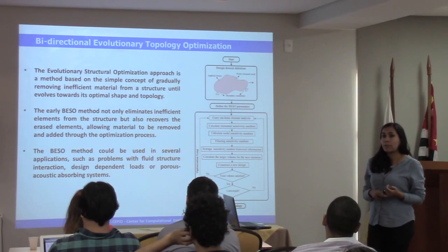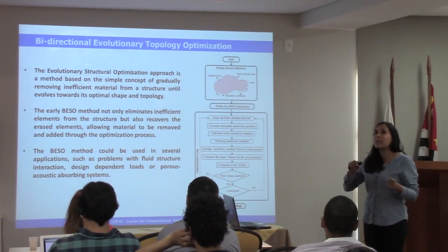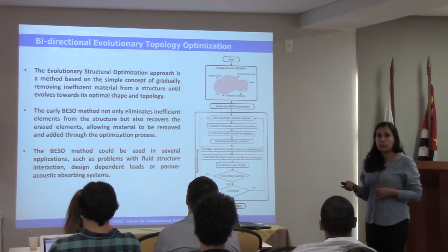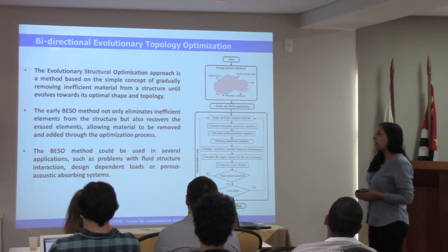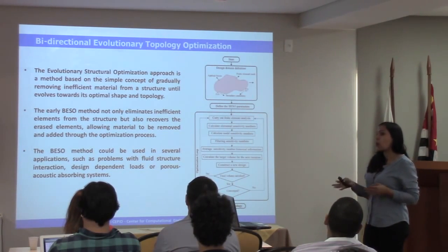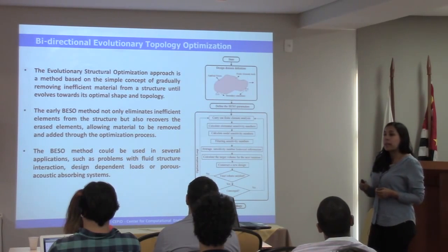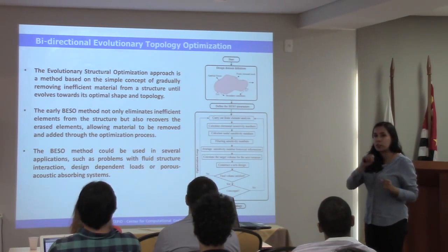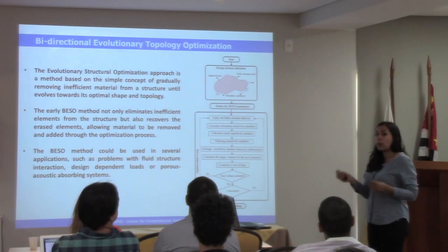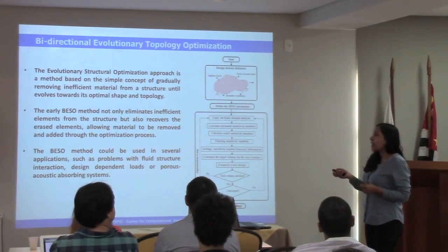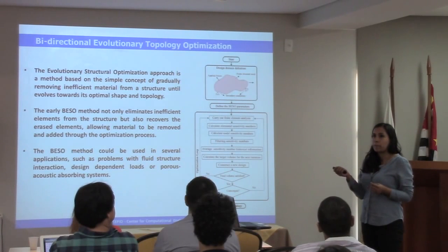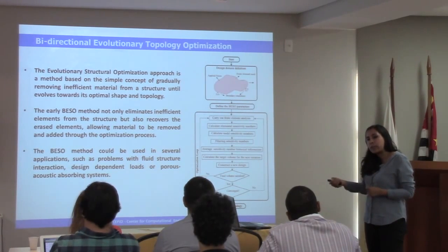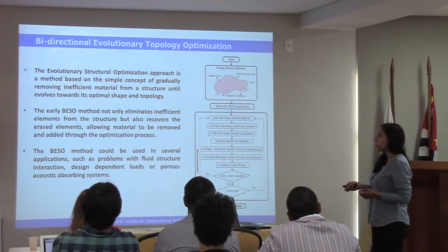To design compliant mechanisms there exist different approaches. There is the ground structure approach, which we'll not talk about, and there is the continuum approach. The continuum approach includes all the optimization methods that are design-based. So what we want is to find a better distribution of material to achieve our goal. What is our goal? Given that it is a compliant mechanism, what we want is to achieve motion. So what we really need is to maximize displacement at any point that we want.